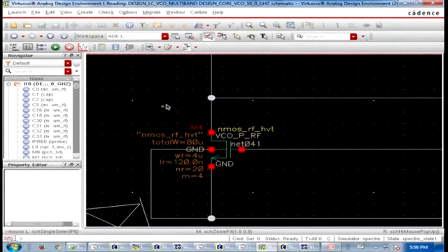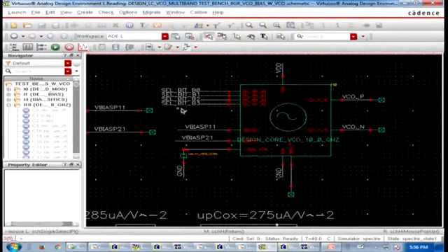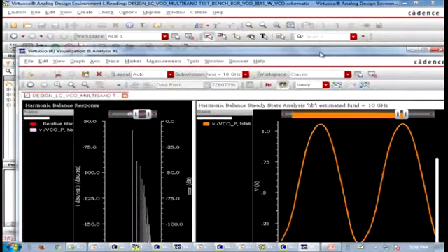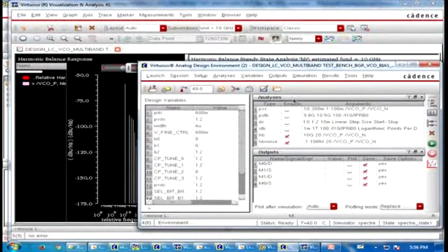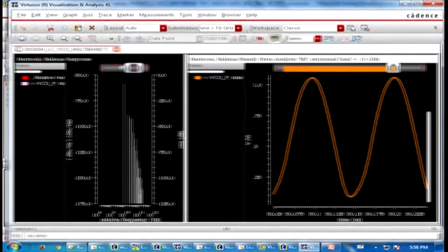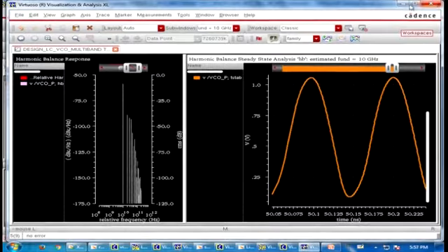And second, we don't have that much time, so better I show you some simulation. We are generally using harmonic balance for our phase noise calculation, and harmonic balance itself is an algorithm, provided by Spectre RF itself, but you have to have a separate license. It's costly.